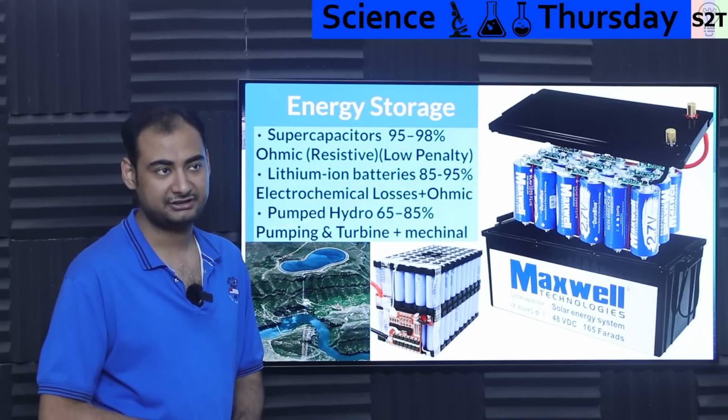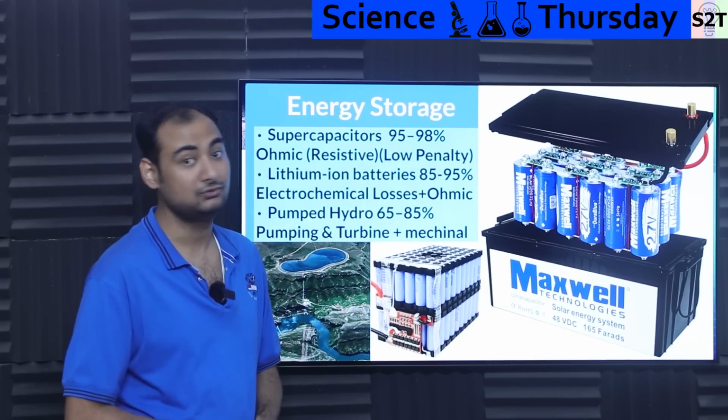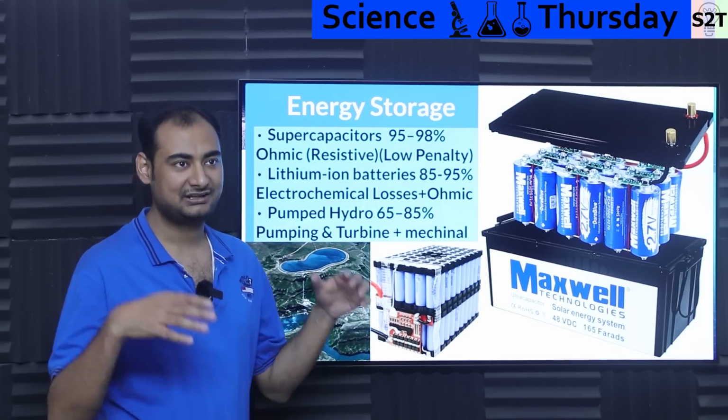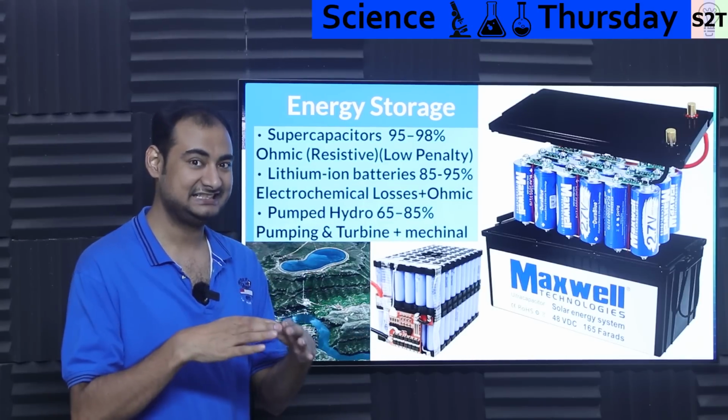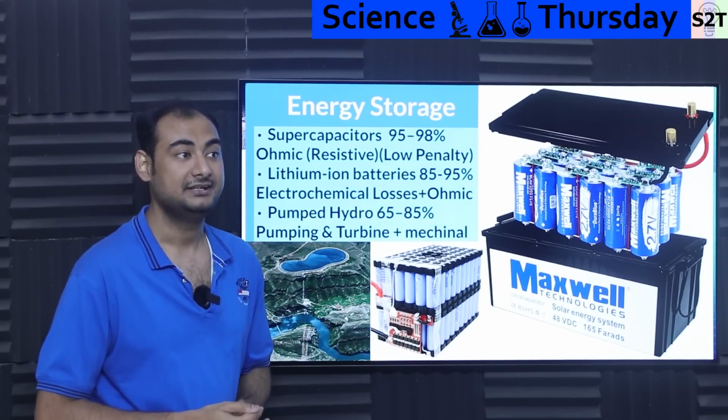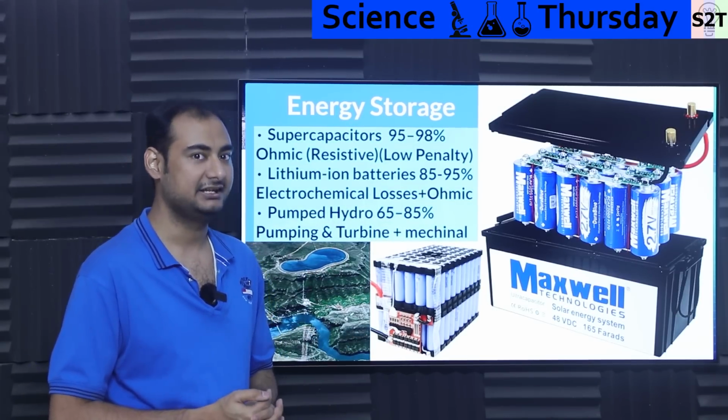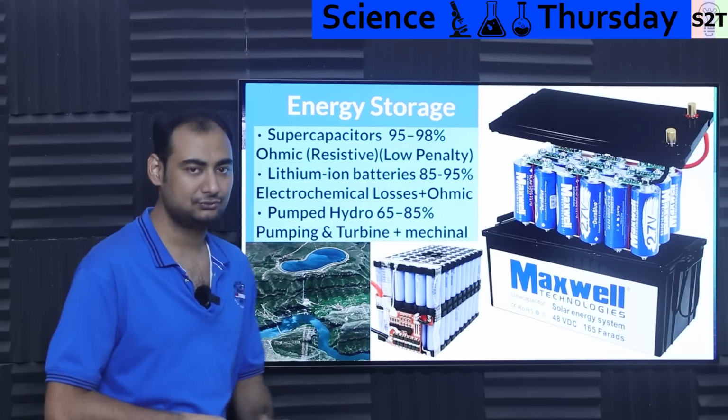Why would you have friction? Well, bearings reduce friction, they do not eliminate it. And on top of that, you have high pressure water, so you have seals there. Those seals are friction points, very high friction points. So you do lose some amount of energy.